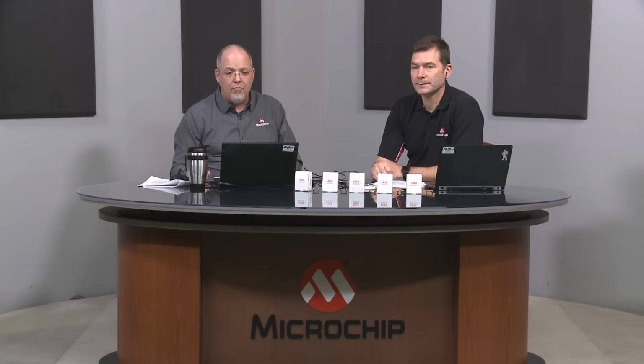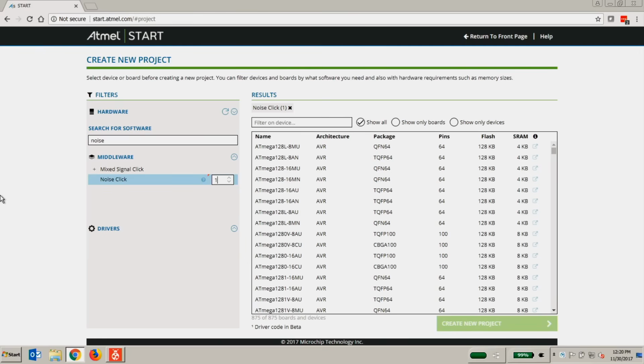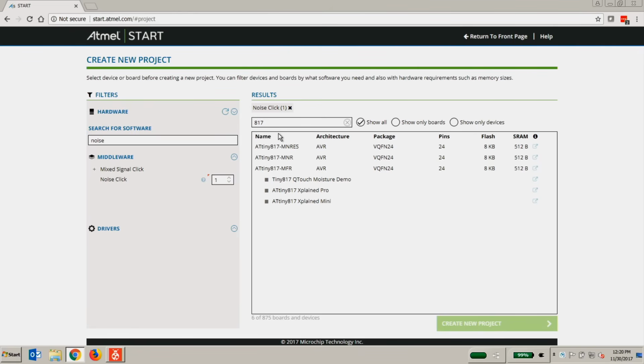Thank you. Just to go back to the computer screen, into Create New Project. We've parsed through the available parts. Since we have the 817 Xplained Pro board, we know that we're using the attiny 817. So I'm going to type that number into the filter on device field, and you can see it parses through all the products and pulls up the available parts that match that number.